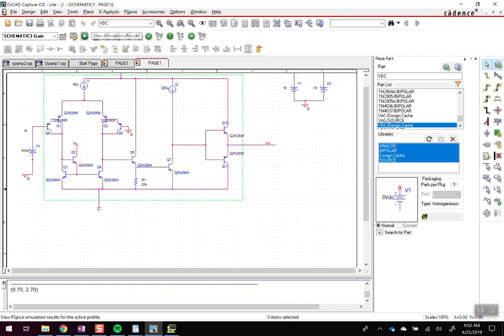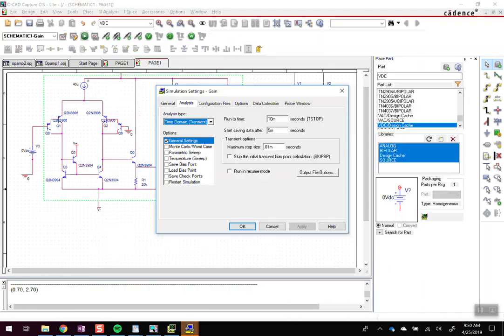It's not letting me look at that. Oh, it's probably because, there we go. So I'm going to be looking at the output voltage, but I'm going to change my sweep here. Instead of doing a time domain, and of course I had to set my time domain up first off because my signal is 1 kilohertz, so I could actually get the signal correctly.